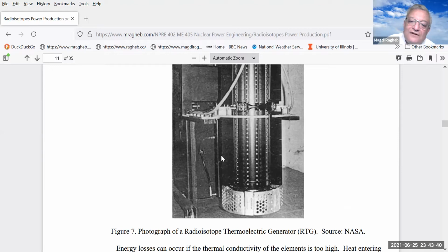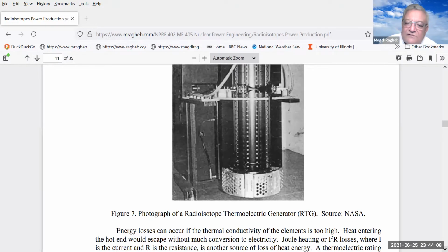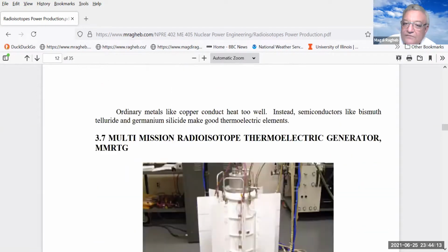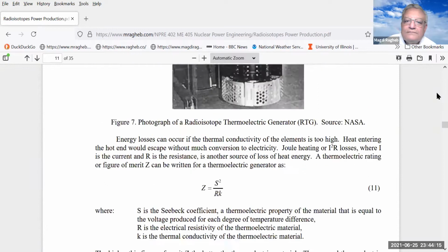And you could see the fins here, like some old motorcycles have been using fins to dissipate the heat from the surface of the engine, in that case, air-cooled engines. Some airplanes in the past also used fins on their propellers to dissipate the heat, and the dissipation in space has to be through radiation. It cannot be through convection. The vacuum of space is a vacuum. Radiation can propagate in it, but there is no convection there.